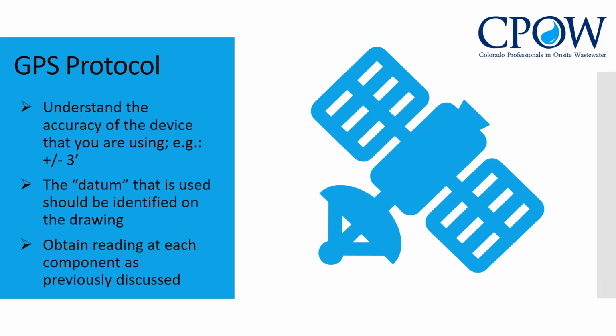A horizontal datum is used to measure a location across the Earth's surface in latitude and longitude or another coordinate system. A vertical datum is used to measure the elevation or depth relative to a standard origin, such as mean sea level, MSL. Since the rise of GPS, the ellipsoid and datum WGS84 it uses has taken the place of most others in many applications. The WGS84 is intended for global use, unlike most earlier datums.